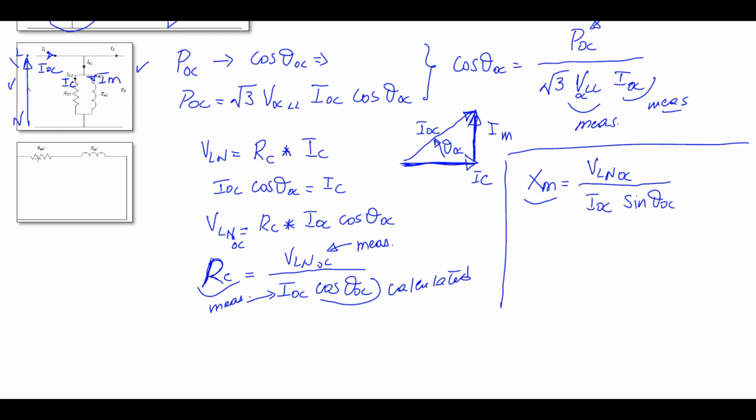Okay, we'll end up with the equivalent impedance where we have R1 and R2 seen from the primary, and X1, X2 seen from the primary side. So this is the equivalent circuit of the short circuit test. The voltage is small as we told, so the losses here will be very small, so we can neglect them. That's why we don't show that part of the core parameters.